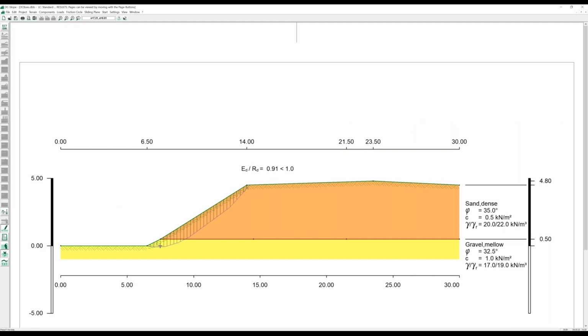the program found a sliding block which is a little similar to a friction circle, but not exactly a circle. And here we have a higher utilization, which means a lower safety factor as a result than we had with the friction circle with 0.8. So this special optimization method found a lower safety than the basic iteration of the friction circle.